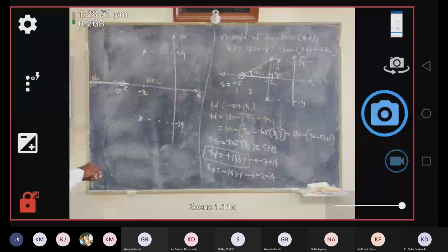Okay, so for this pole, draw the reference line, and for minus 2 plus j4, it is 143.1. So that means plus angle. So here is 180, here is 90. So somewhere here like this, you just take the measurement. So this is the angle phi d, 143.1, that is phi d, that is plus.